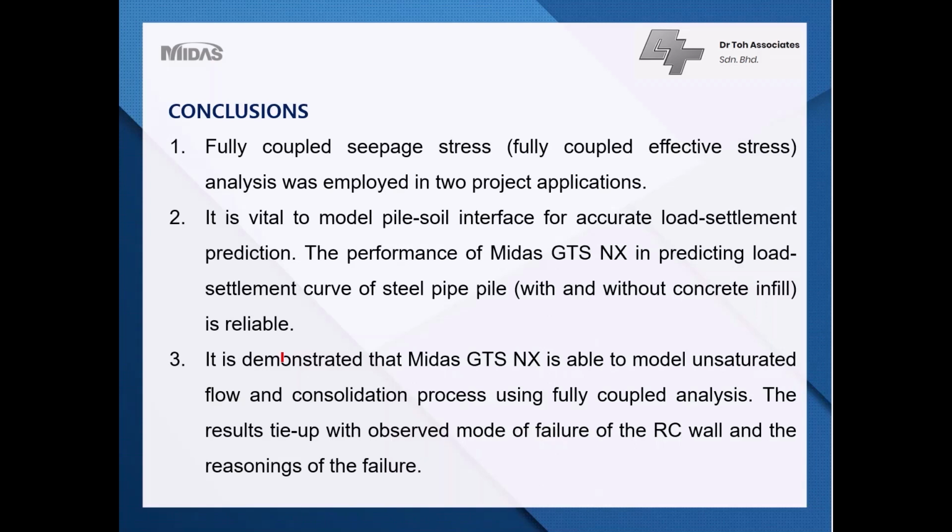The performance of Midas GTS in predicting a load settlement curve of the steel pipe pile with and without concrete infill is reliable. And number 3, it is demonstrated that Midas GTS NX is able to model the unsaturated flows and the consolidation process using fully coupled effective stress analysis, and the results tie up with the observations, especially on the mode of failure, on how it translated and rotated.